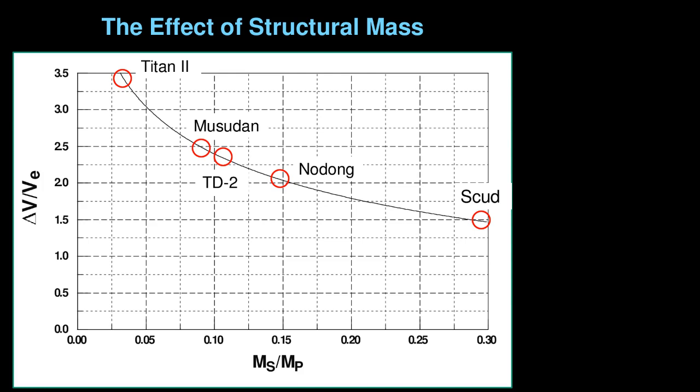And I would just say part of the reason it's hard to build an ICBM is again this notion that as you start to add fuel, you have to lift more mass, the rocket needs to be stronger, the rocket structure has to be heavier, and so as you start to scale things up, you hit diminishing returns, and that's why it gets difficult. If you look at a modern space launcher, a useful rule of thumb to keep in mind is that it's roughly 90% fuel, 10% structure, and only about 1% payload.